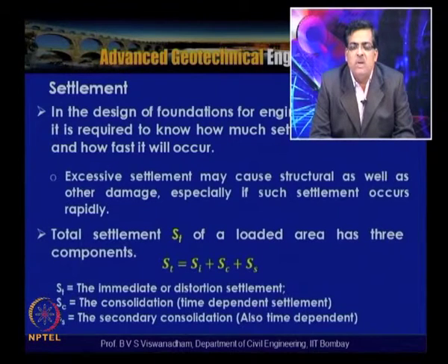This is evident in examples like municipal solid waste, a man-made material, which will undergo very large secondary consolidation settlements because of its own characteristics, the heterogeneous mixture of the matrix, as well as the ongoing biodecomposition because of the biochemical changes happening in the municipal solid waste with time.